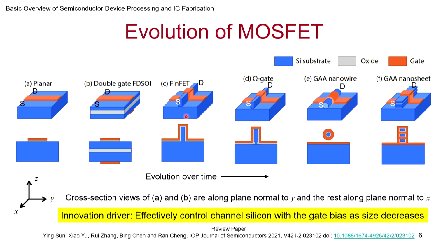So what they did was they tried to build these fin-like structures that are sitting on the substrate. And notice the source and the drain are in this direction. The gate is wrapping on 3 sides of the fin. Initially, they just were using the 2 sides, but eventually they use the 2 sides as well as the top. Why waste the top as well? So you have a thin oxide, gate oxide all around this fin. On top of it is the poly, which is patterned as is shown. This is what is the FinFET. The cross section of this is shown here, if the cross section is taken, as I said, perpendicular to x in this case.